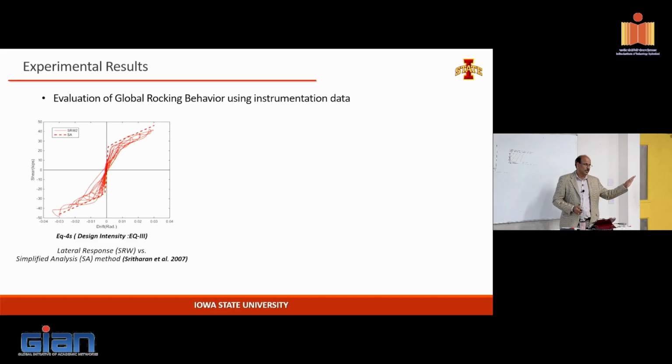But even though we subjected that wall to the design earthquake and the corresponding energy dissipation appears small, that wall actually came to rest after some cycles. So then one questions, what I said at the beginning, okay, how much damping do we need? And what was the disadvantage of reducing the damping pretty significantly with a single rocking? How much energy can you actually dissipate through the single rocking?